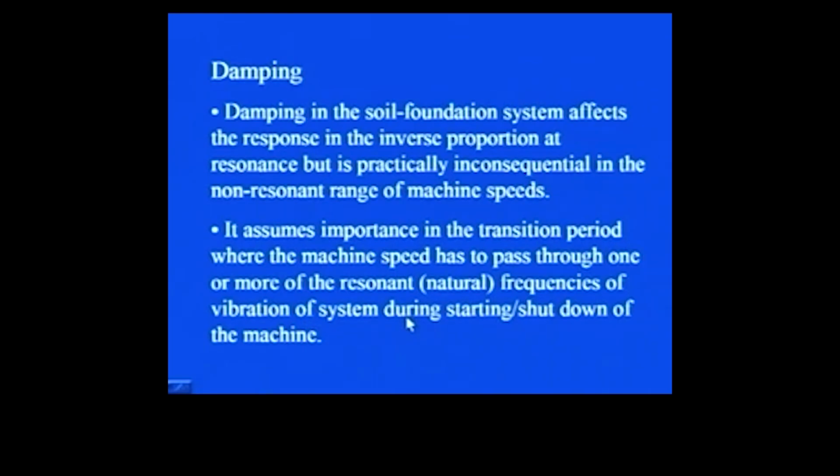You see, when you either start or shut down the machine, what happens is that when the machine picks up its speed, it crosses some of its natural frequencies. So, at that particular point of time, whenever it is crossing its natural frequency, the damping becomes quite important.